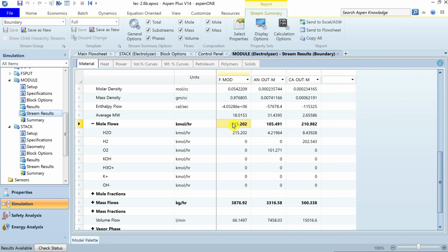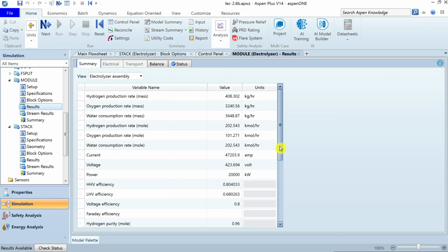The additional water and potassium hydroxide are neither calculated nor defined in the stream summary results. So that means virtually this module can be used for the simulation of other types of electrolyzers other than alkaline electrolysis, considering that the geometrical and electrical parameters, though not defined in case of the module, fairly correspond to the alkaline electrolyzer. One very important parameter for comparison is the heat duty in both cases.